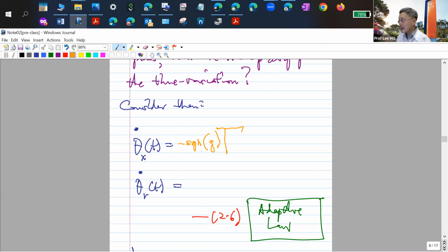Then what happens is, remember we had the tracking error. Now there will be an equivalent tracking error. The tracking error will be in all the state variables. I'll talk about that more in a moment. So this is a whole vector of tracking variables. Then it will be E transpose P, a symmetric positive definite matrix, which I'll tell you about in a moment. Then times the B input vector of the system. Remember we said B was known, and that's realistic for a large class of real systems. And then finally, your full state variable, which is measurable.